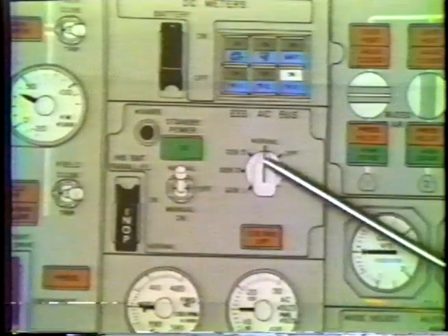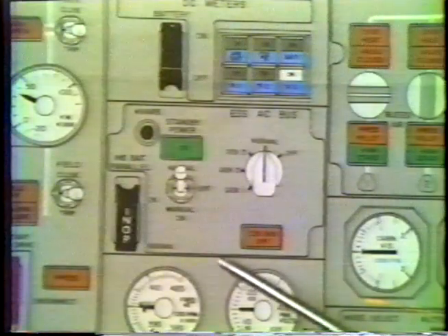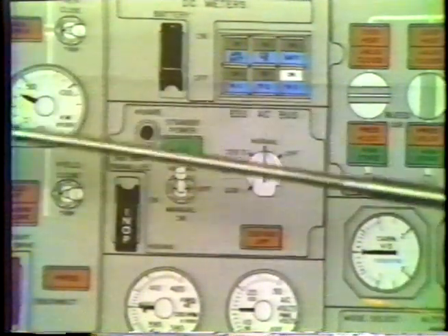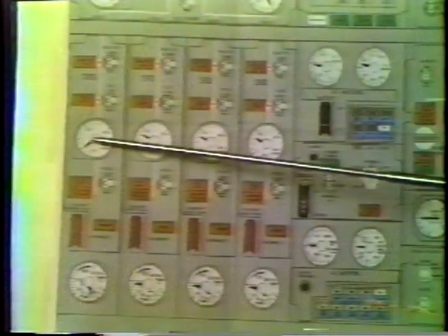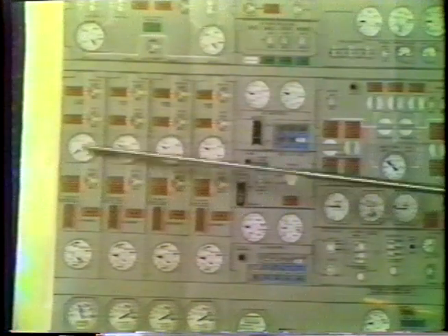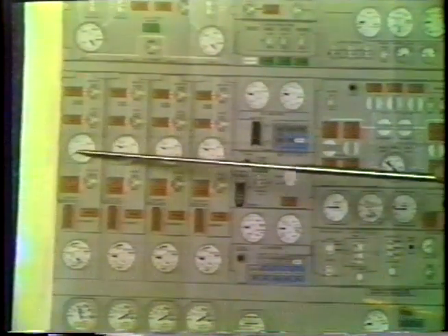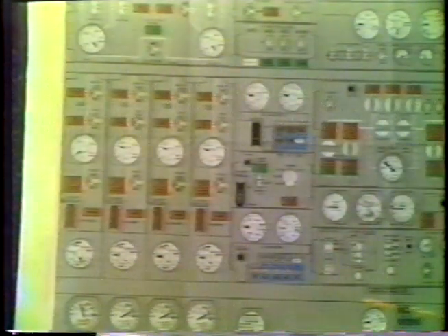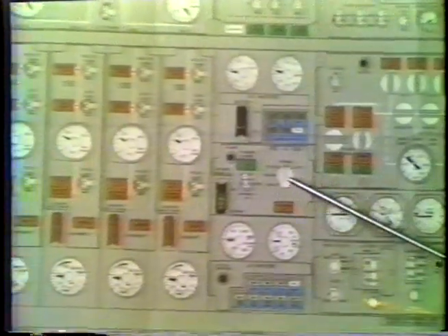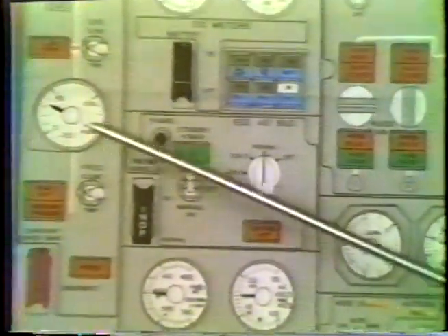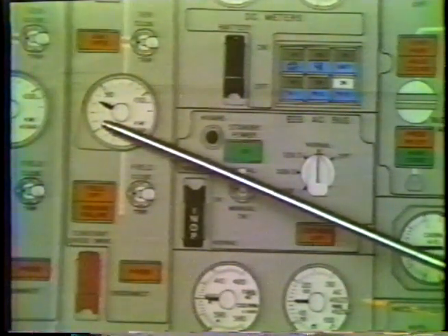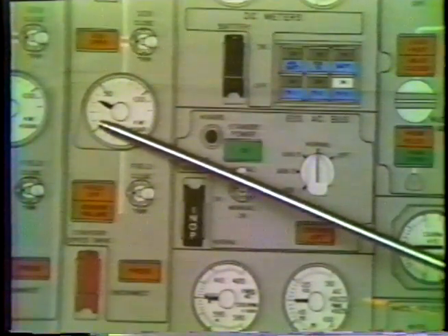Selecting generators 1, 2, or 3 will put the essential bus directly on the output of the generator. The way I like to think about it is it's coming right out of the meter before the bus. And you will see a reflection of that load in the meter if it was selected. The essential power takes a very low amount on the load meter, essentially 2 or 3 kWs, which is a very small amount, approximately a needle width.